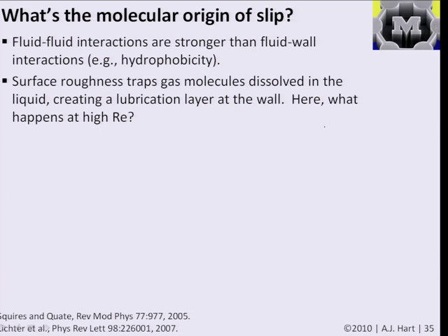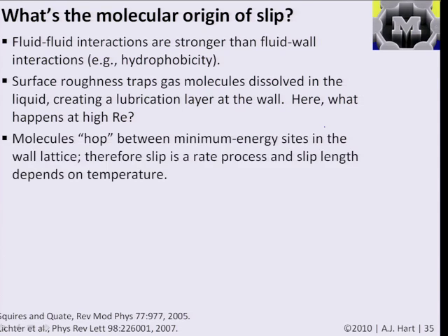This is also practically important for things like designing surfaces for drag reduction for underwater vehicles and for ships. And there's a big difference here in the behavior at low Reynolds number and high Reynolds number. These kind of lubrication layers tend to break down when the flow velocities are higher.